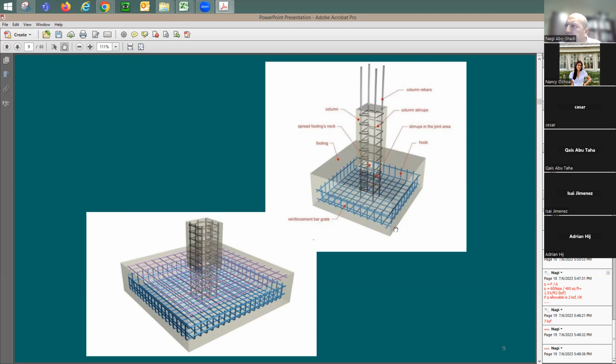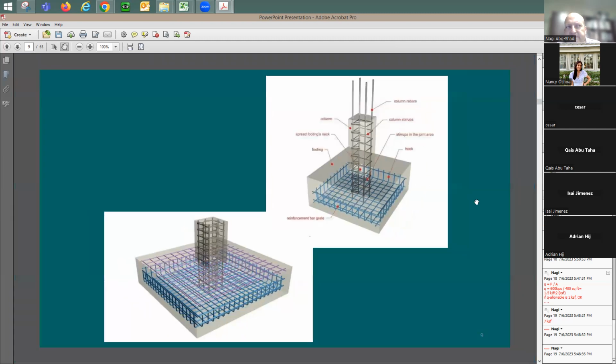This is the mode of failure with the soil, provided that the footing itself is strong, thick enough, and has enough reinforcing, so nothing wrong happens with the concrete member itself. For the sake of this course, I have two issues: sizing the footing, length and width, and the second is design of the footing as a concrete member, and then we need to see how we can design it.